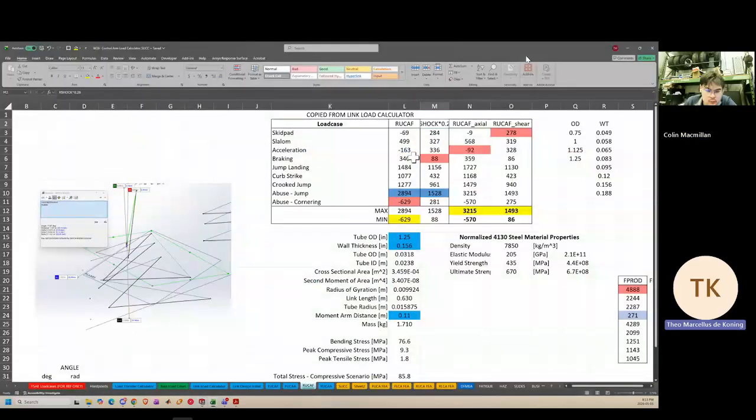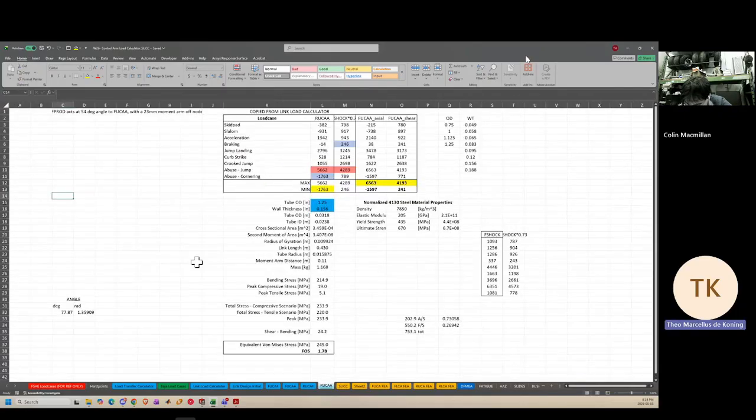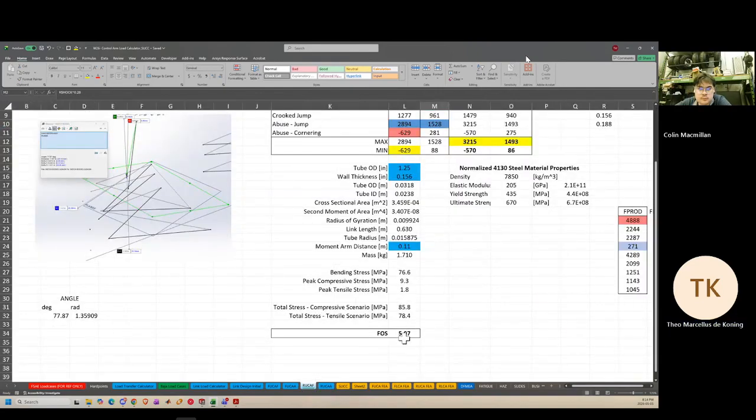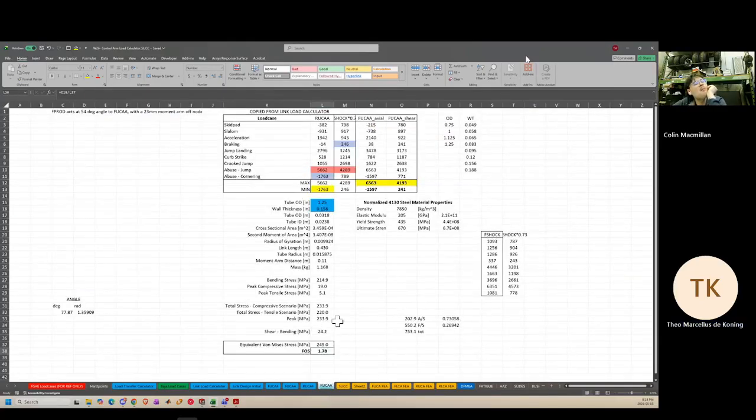So you'll get 3 times the forces on the one side. From which side, the fore or the aft? The aft one will take more force because it's closer. Okay. Yeah. Is that true? 517. Yeah. Like the fore link on the rear, minimum factor of safety of 5, and the aft link like 1.8.